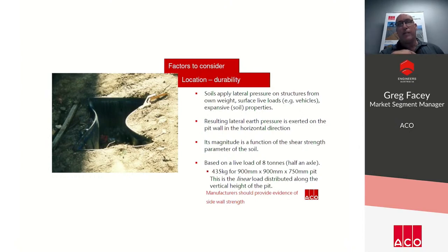Historically, we've seen pits in expansive soils applications where they haven't been installed correctly, particularly plastic single wall pits, during rainfall events where the soil becomes expansive. It pushes the walls of the pits in, but once it's dried out, the pits have come back to shape again. So it's an interesting concept that we need to make sure that we consider not just the pit strength, but also the location and all the surrounding forces that will affect the durability of the pit. And manufacturers should be able to provide evidence of sidewall strength.